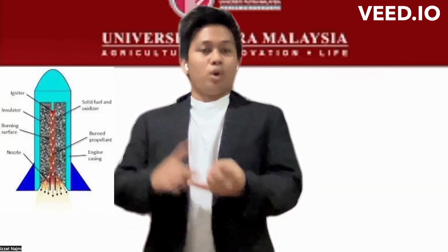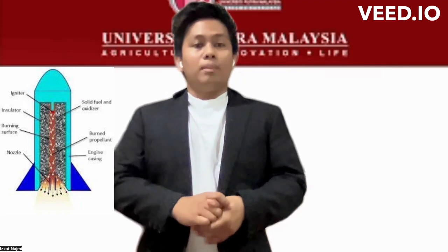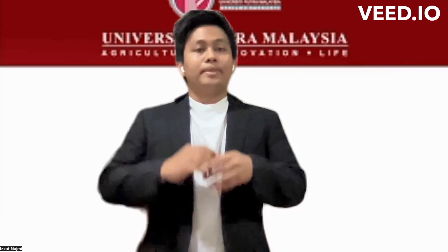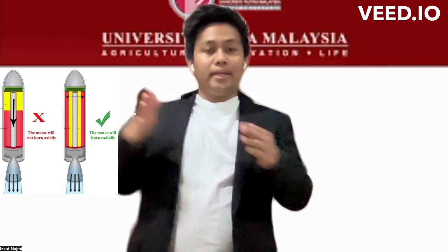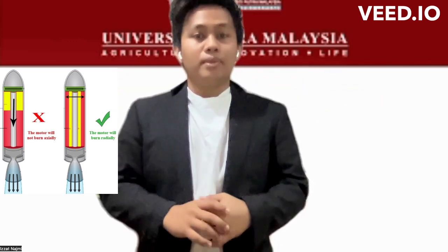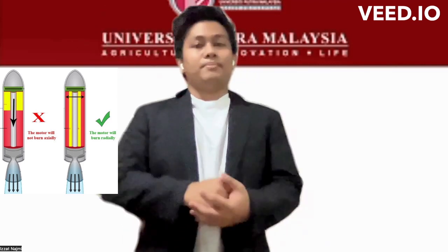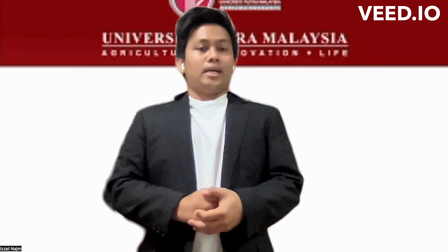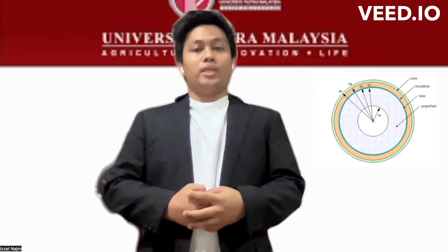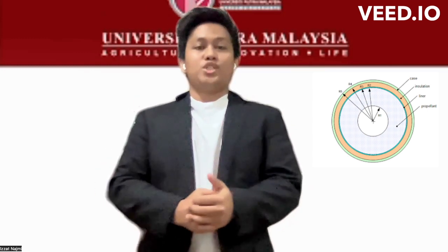A rocket motor consists of propellant grain, liner, insulator, motor casing, and rocket nozzle. The most crucial parts in the rocket motor are the liner and insulator, as the selection of the material is very important here, because the propellant burns radially from the direction of the propellant grain. It will produce high temperature and pressure. The insulator inside the rocket casing must have good thermal insulation properties in order to protect the outside casing of the rocket motor from the high temperature and pressure.